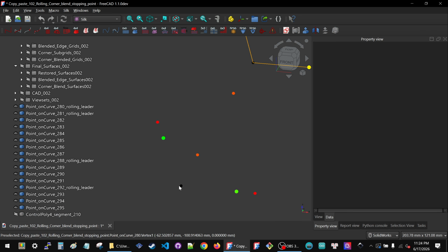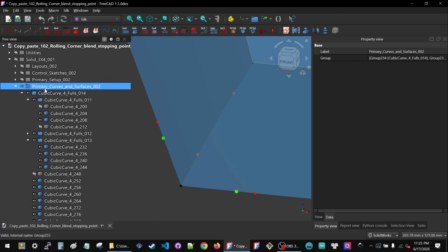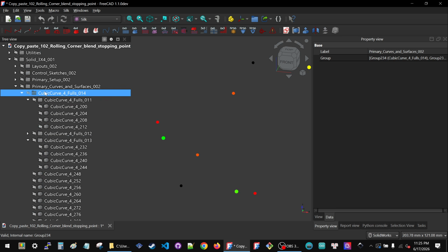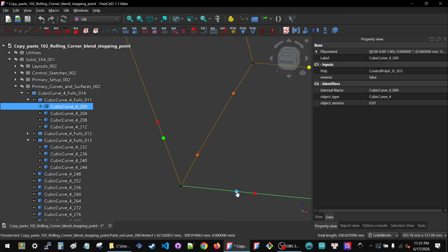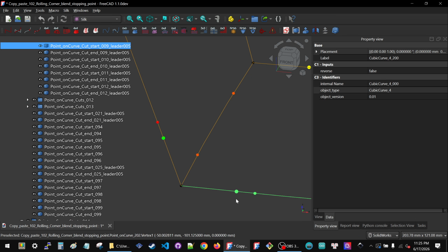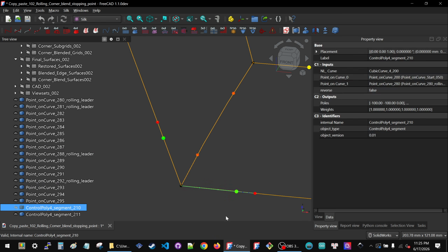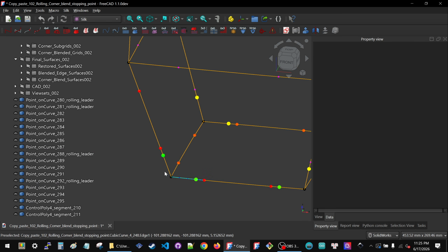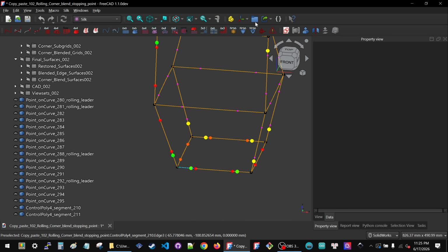And now for these 2, I don't have the problem of all the curves running into each other, and I don't have the problem of the start point being there. So this one is more reasonable. I can just select this point, select the curve, control select this point, control select this point, create my segment. And now I have my 2 segments here, and that's what I need to do on all of those eventually.